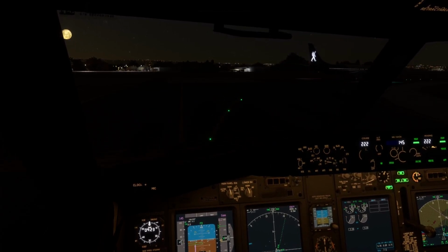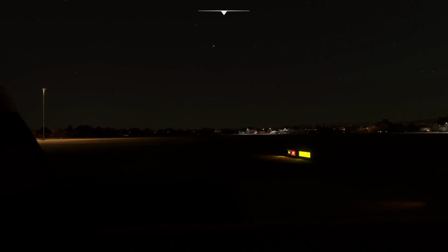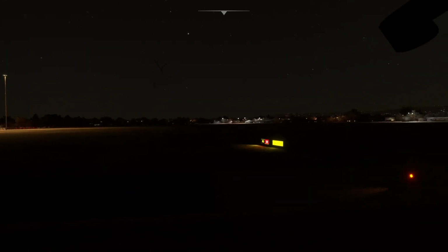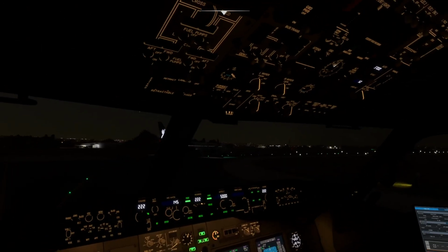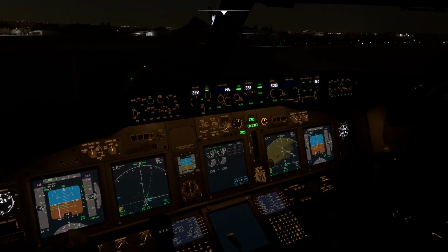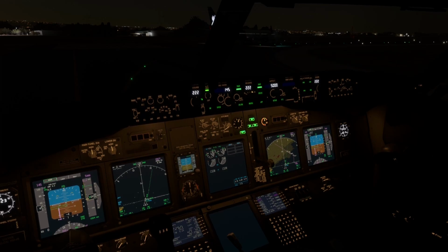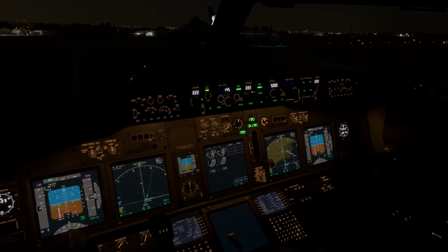Now, my first payware aircraft was the Phoenix A320, and that's where I learned how to properly operate an Airbus. You know, DIFSRIP, the acronym for programming and setting up the MCDU, proper rotation technique, 2.5 to 3 degrees per second, managed modes, LAND review from this, VERT review from this, anchor time points, secondary flight plan. All of this you won't get in Infinite Flight.